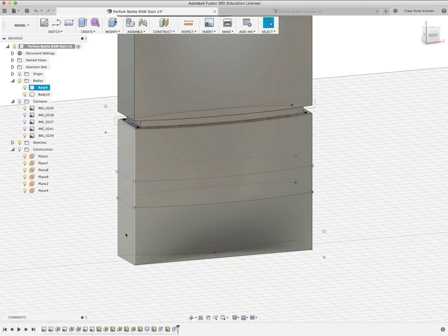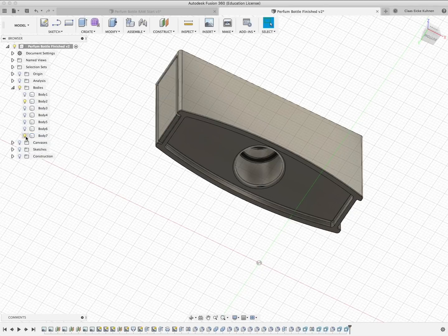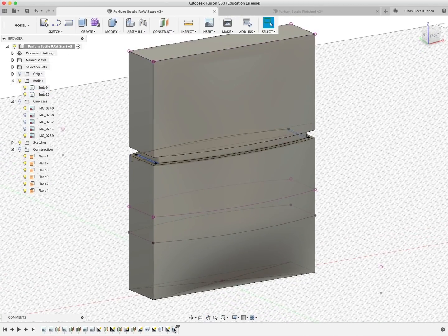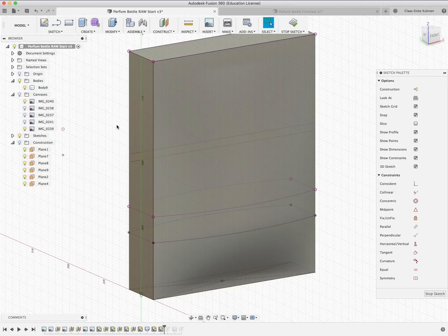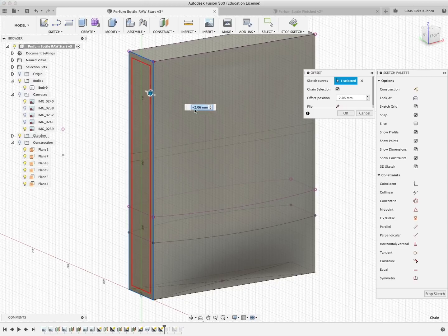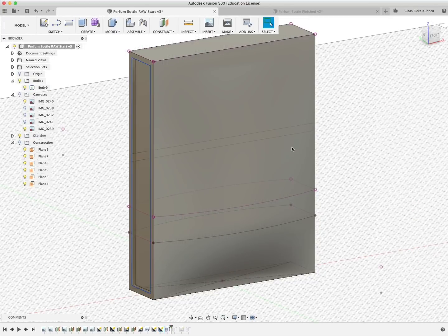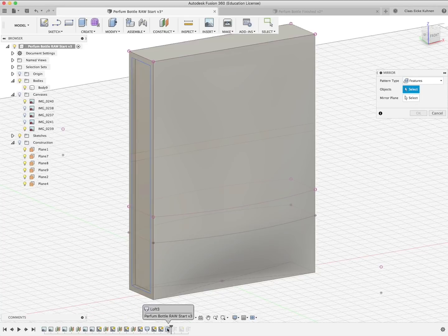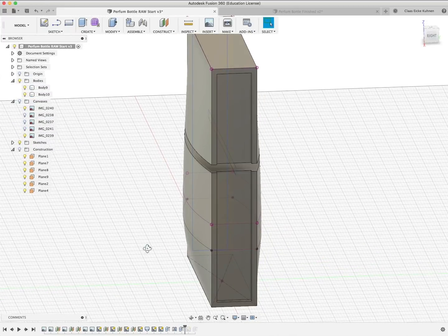At this point, one might think, oh, I forgot that we have these cuts here at the sides. So what's now the best way to create these cavities into this body? Well, I could cut into this afterwards, or in parametric modeling I could simply go back in time to maybe there, where these cuts are not done yet. Here I first create the sketch, offset a face. I go down by -2. Very good. Then I cut in -1.5 millimeters. Very nice. And now I will mirror this extrusion feature across the construction plane to the other side. Okay, and then we can go back.